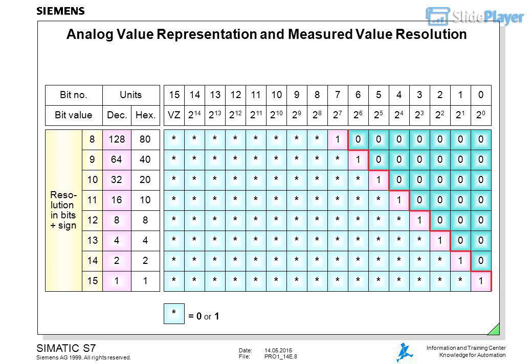Conversion time: the conversion time depends on the conversion procedure used in the module, integrating procedure, successive approximation. The conversion times of the different modules are given in the S7-300 manual. Example: the SM344 has a conversion time of only 5 ms for all 4 input channels.